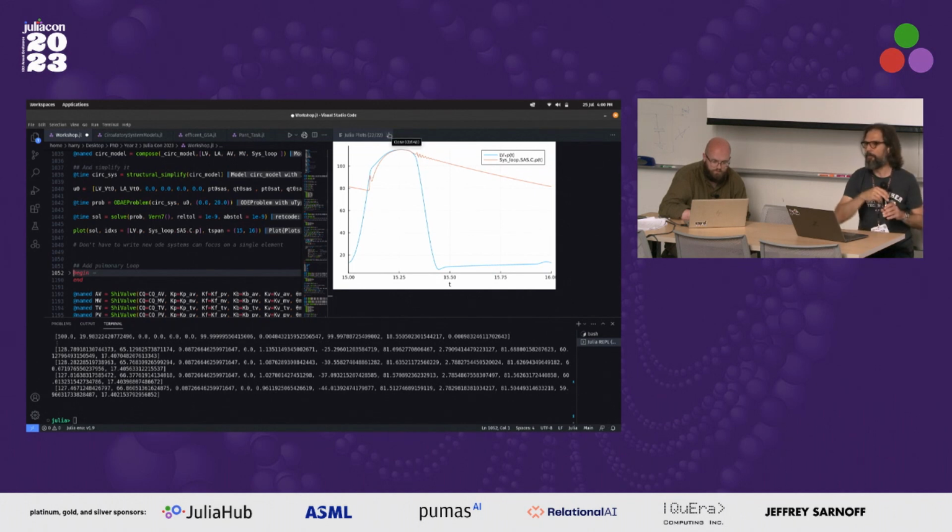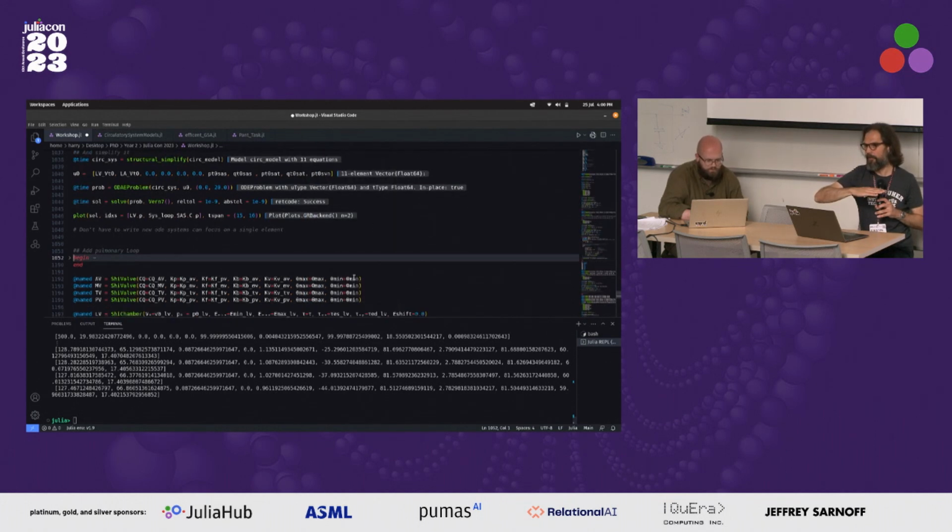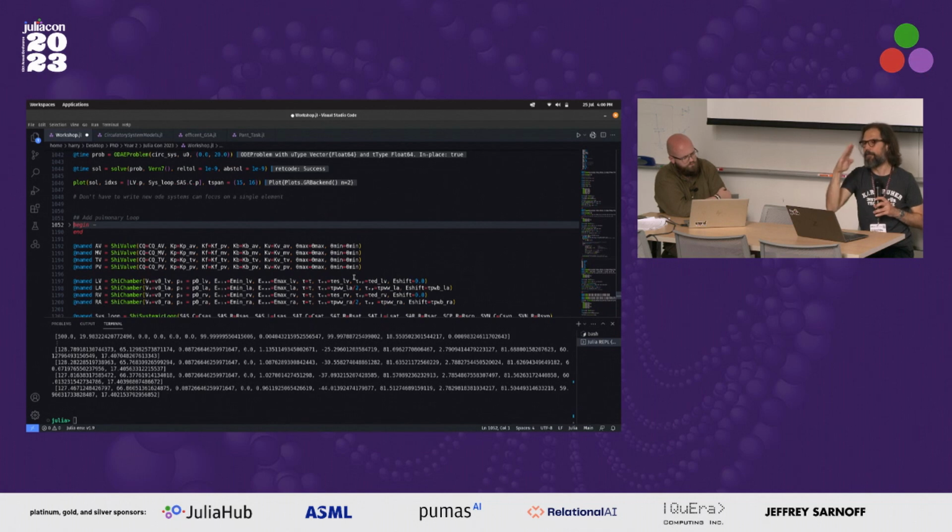So we need to overcome the initial inertia of the valve, and then it opens, and then the pressure drop over the valve goes back, and then it builds up as we accelerate when we go into that square root term. Because the resistance is dependent on Q squared. So once it starts flowing, resistance builds up, and that's where the pressure increase comes in again. But this first blip, that's just getting the heart valve to move from rest.